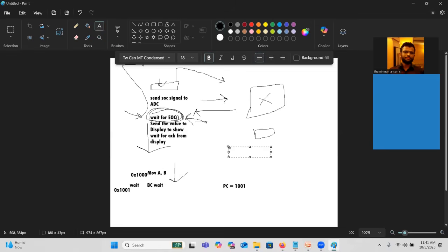Let us say the receive register, the RC register, contains the content capital A. It has received capital A, which is a successful reception. Once that happens, you can configure a serial port receive interrupt that will load the program counter value to 005. So at memory location 5 in program memory, I will have a branch to ISR.